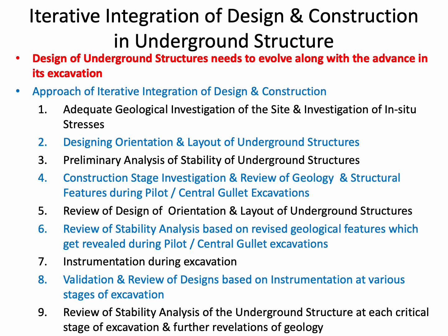Construction stage investigation and review of geology and structural features during pilot or central gullet excavations need to be done. Review of design of orientation and layout of the underground structures as the need necessitates. Review of stability analysis based on revised geological features which get revealed during pilot or central gullet excavation.